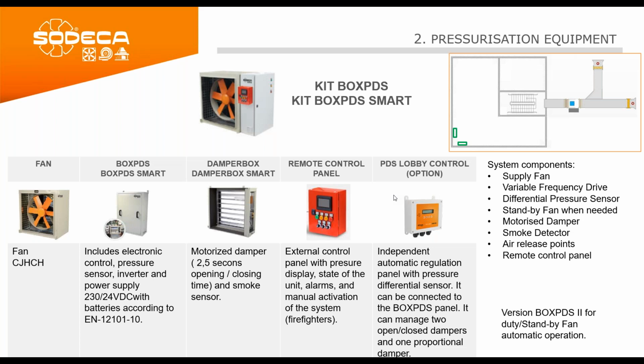We can pressurize all the lobbies at the same time, or we can pressurize only the lobby at the fire level. But then we need to control the pressurization level at this lobby. So we need one of these devices at every lobby, and the speed of the fan will be controlled by the pressure difference that the PDS lobby control gives at the lobby of the fire level.